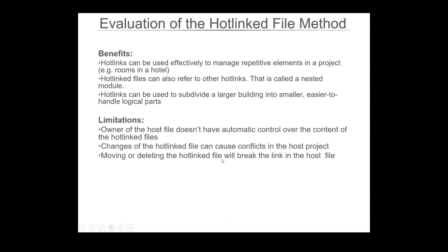And moving or deleting the hotlink file will break the link in the host file. That's if you have the hotlink file hosted on just a normal server rather than, say, on the BIM cloud server, or even on the BIM cloud if you move it to another directory. If you move the hotlink file from one folder to another, ArchiCAD will always be looking in the original location. So you would then need to go into ArchiCAD and tell it to look for this hotlink in another place. Basically, use the relink command if you ever lose your hotlink.